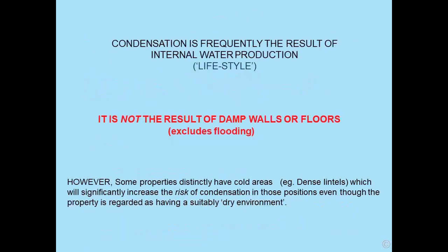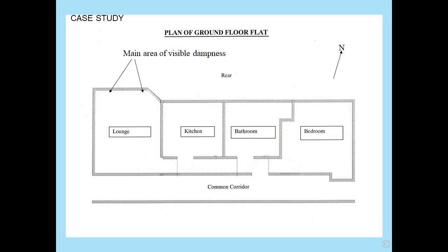Just as an interesting case study, condensation is frequently the result of internal water production. It is not the result of damp walls or floors, and this I exclude flooding. But I do mention that some properties have distinctly cold areas, such as dense lintels, and that will significantly increase the risk of condensation, even though the property is regarded as having a suitably dry environment.